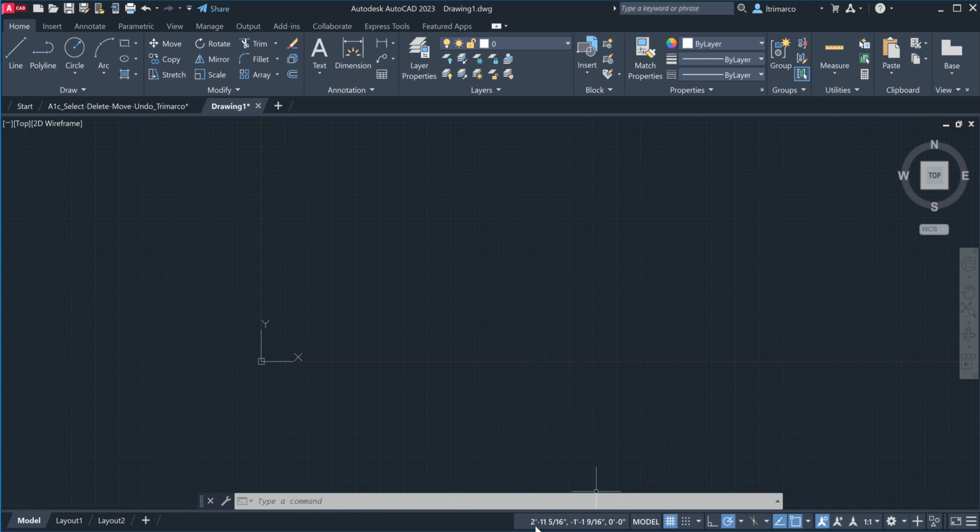What that's going to do is give you, at the very bottom, almost center of your screen, the coordinates of X, comma, Y, comma, Z. Z is always going to be 0 feet, 0 inches for us for the whole semester because we're not building anything in 3D in AutoCAD. Hopefully by the end of the semester you'll see a little bit of 3D in SketchUp. Anyway, with that said, it's kind of nice. When I move my cursor around, it also moves, so it's a nice placement.